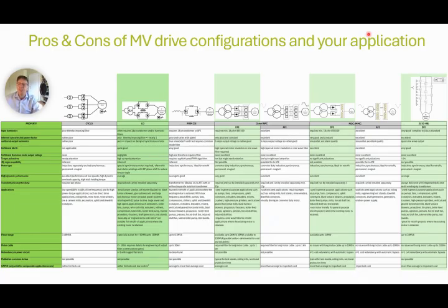The Cycloconverter, the load commutated inverter and also the PWM CSI are what we call inherent 4-quadrant drives. Their configuration allows energy to be sent back to the grid. The other topologies, 3-level neutral point clamped and multi-modular converter, require an active front end. The 2-level series Cascaded H-bridge is not readily available for 4-quadrant operation. Because of the lack of a common DC bus, braking even via dissipation in a resistor becomes quite tricky and often economically unviable.